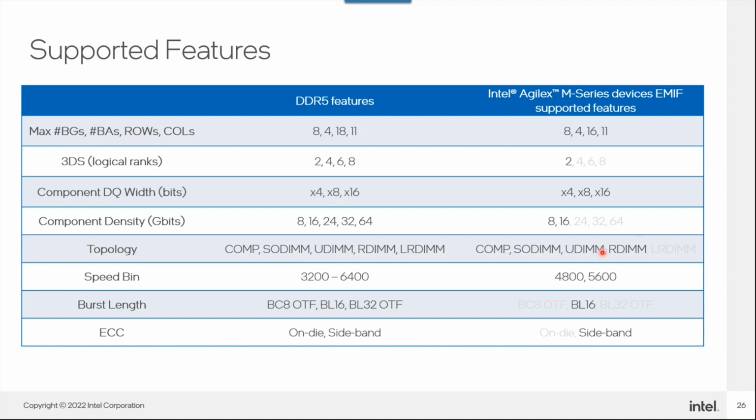It's the dev kit. It should be okay, right? Yeah, it should be okay, but I need to just see how they have placed the pin. We have designs. If you can tell me which exact, it's a different pinout from the dev kit. Okay, okay. So I need to see the pinouts to make sure that there is no IO sub bank sharing happening.